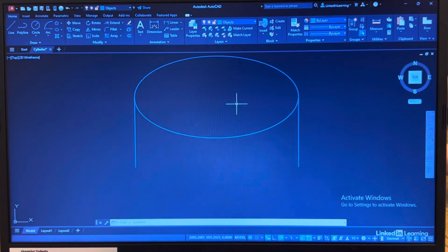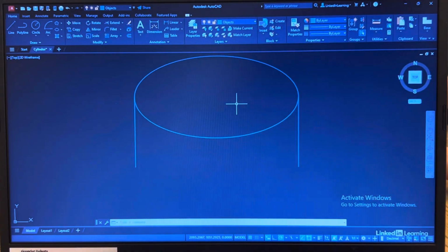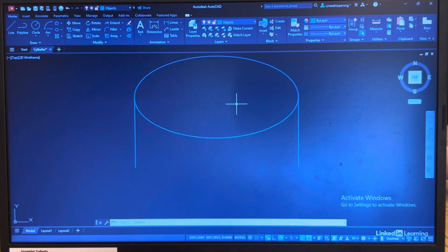So it now looks like the top of a cylinder. And it's the circular top of a circular cylinder, but imagine you've rotated it through 60 degrees to look at the top of it. That's exactly where you're coming from with ellipses. Ellipses are incredibly useful for this. We now need to create an elliptical arc. Now, the way to do this is very quick and easy.